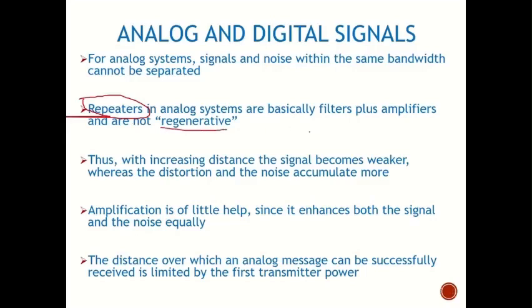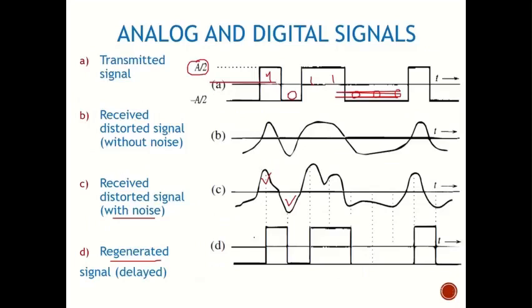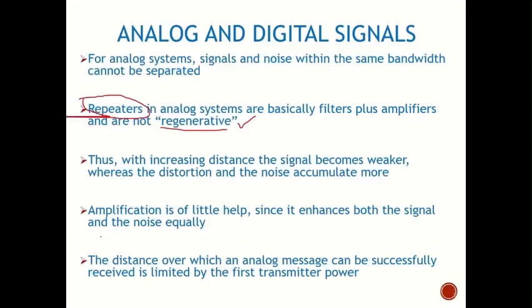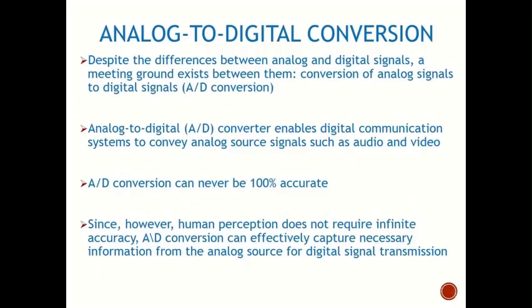It is generally used to increase the length of the system, and this results in improvement in signal to noise ratio, because once we have got our signal back like this, the signal to noise ratio will be improved. If you are only performing amplification, this will not improve the signal to noise ratio. It will only amplify both the signal and noise.